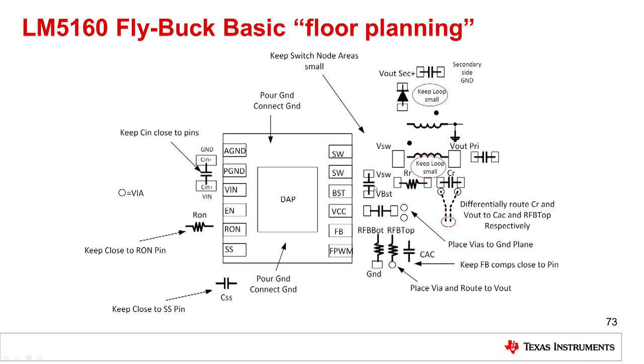Again, most converters require a bootstrap capacitor, which also needs to be physically close to the regulator, so that it can be connected to the switch and boot pin with very short and wide traces. If we're looking at a Flybuck or Flybuck boost that has a transformer, we want to make sure that the loop area here on the secondary of the transformer is kept very small, which means keep the diode and the output capacitor close to the secondary.